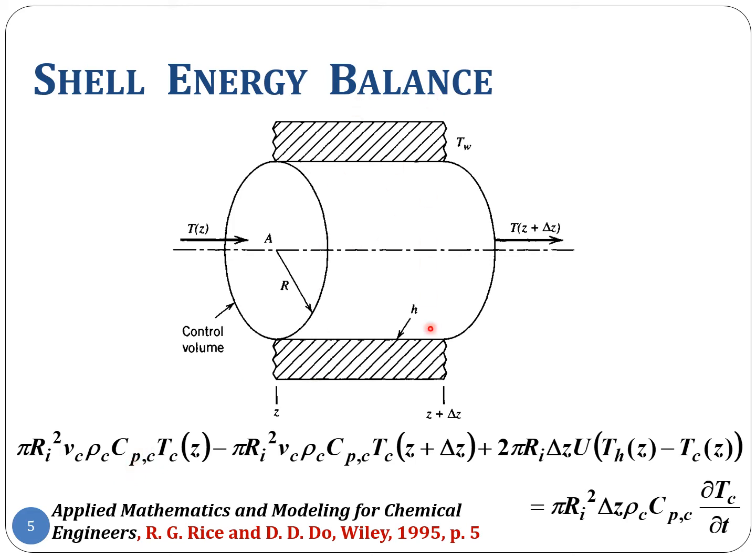At any cross section there is a constant pressure, and therefore there is a pressure difference that drives the flow. So the specific heat capacity is evaluated at constant pressure, and then this T is the temperature of the cold fluid, and all these C subscripts indicate cold fluid, whereas the subscript H indicates hot fluid. Now, of course, there has to be Tc minus some reference temperature. But that reference temperature is not considered, because it will be there in the other terms also and will get cancelled.